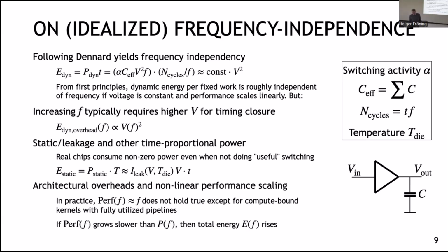And last but not least, we also have other architectural components which are not only processing. In particular, memory and all these uncore units will, in an easy model, consume some static power, which will also contribute to your overall power consumption. These are all reasons which add up to be frequency dependent, while the underlying capacitor charging and discharging should not be frequency dependent. So I was pretty much convinced that we have a dependency on frequency going on here.